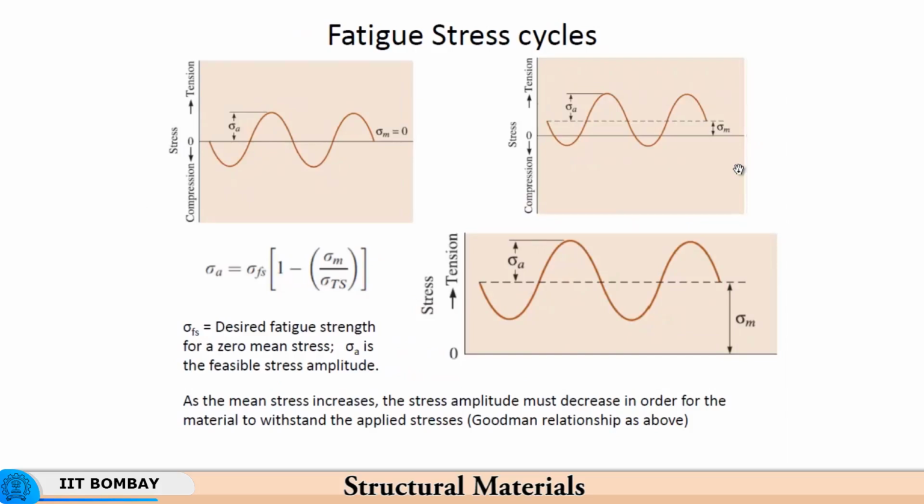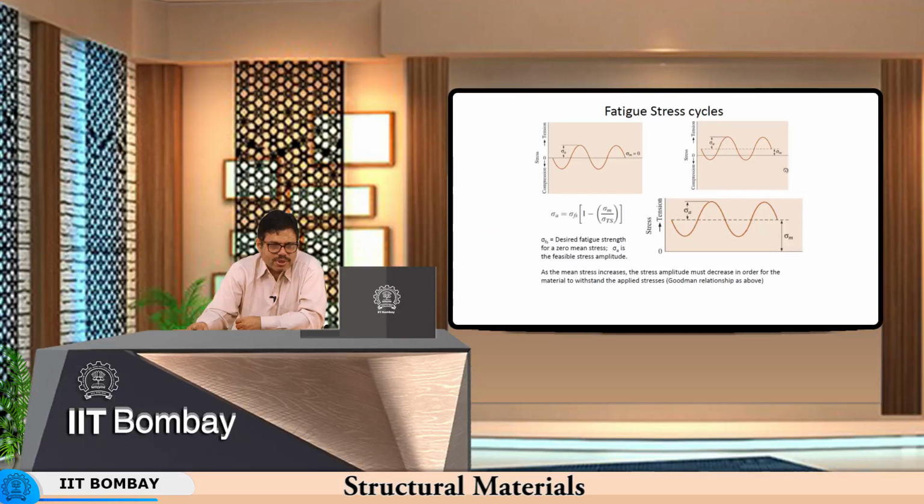Now, if you have fatigue damage taking place in a rotating bending type of fatigue, this is the kind of fatigue cycle, because when you rotate something and it is being bent, the outer fiber goes into compression for a while and then it comes to the other side. Once the shaft rotates by 180 degrees, it comes to tension, again it goes to compression and so on. The tension and compression have the same magnitude, and therefore, the same magnitude of stress is experienced in both tension and compression. So, R becomes equal to -1.